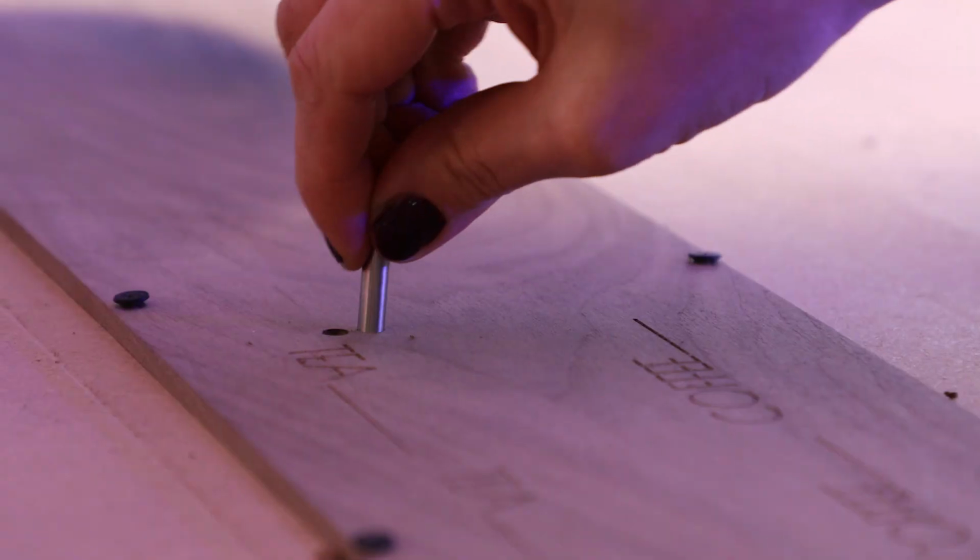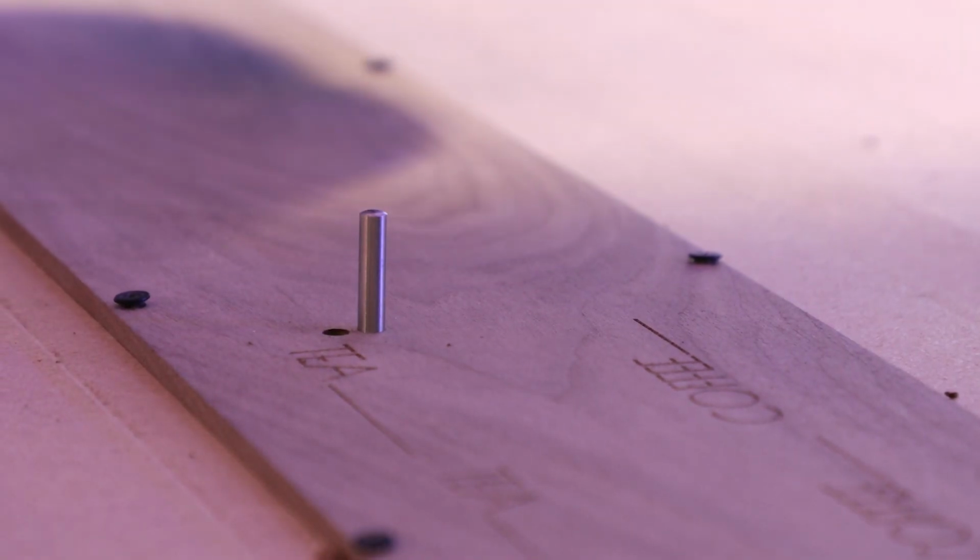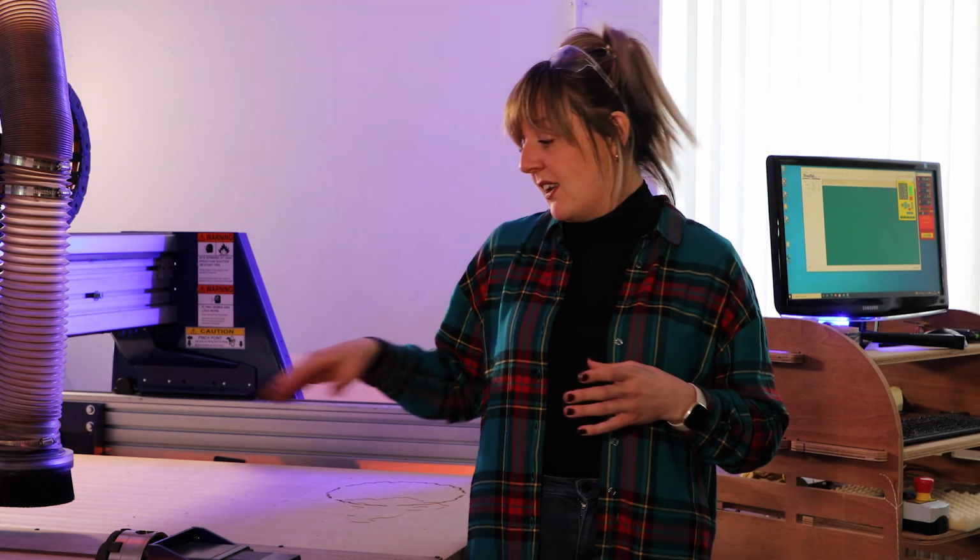The second one, however, we've got a little bit of an allowance, so we've applied a little bit of an overcut to that. And this one actually fits really nice. It goes in nice and easy. It's still tight. We're not forcing it in like we are with the first one. So we're going to go and just rearrange our file to make sure that the holes that we cut for the final coaster base have that allowance in so that we can easily slot those pins in.